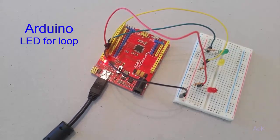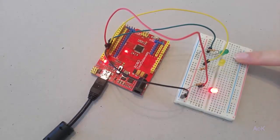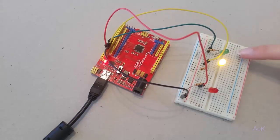Here we're using a for loop to tell the red light to blink 5 times, the yellow light to blink 3 times, and the green light to only blink 1 time. I also changed the delays to make each one blink for a different length of time.